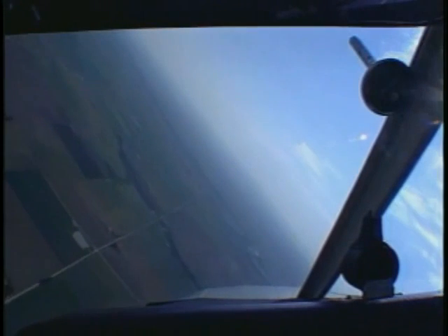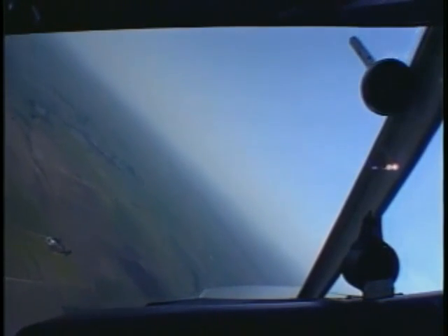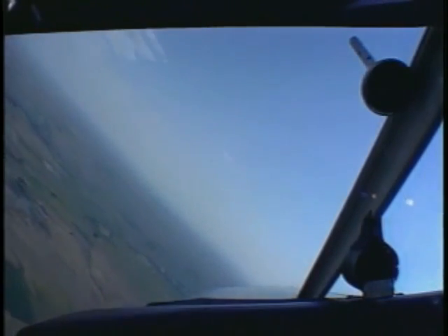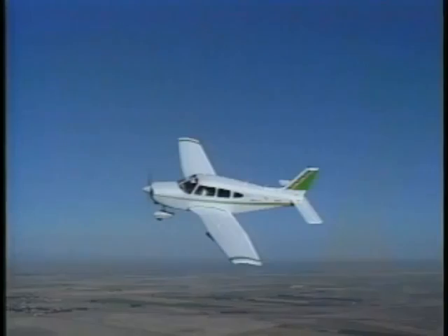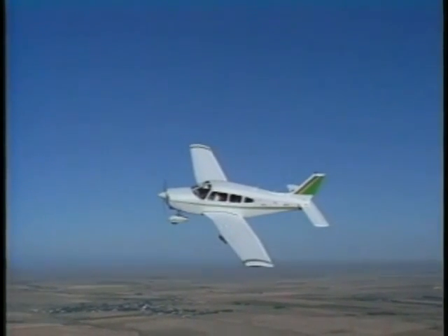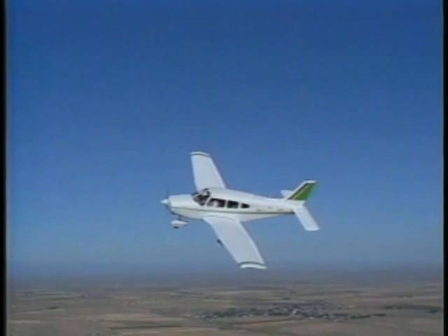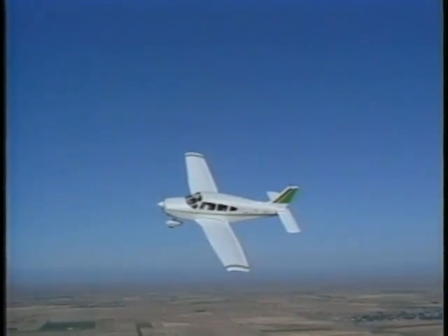To properly regain altitude lost during a steep turn, begin by decreasing the bank angle to reduce the load factor and allow the pitch attitude to increase. Once you've returned to your desired altitude, re-establish the bank angle and apply the proper back pressure to re-enter the maneuver.